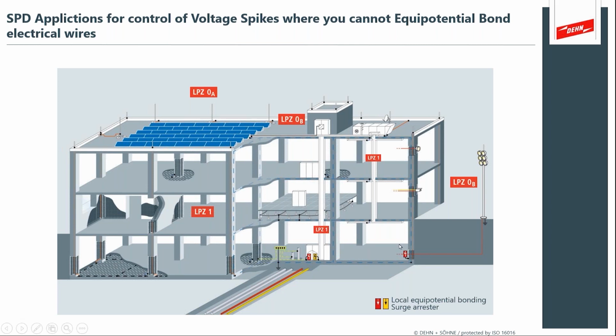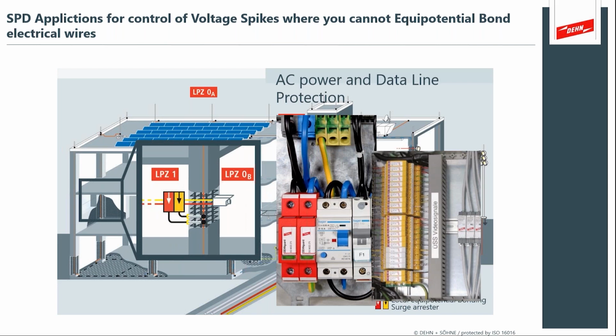And that's what an image like this is showing: you look at all of your apparatus and you apply appropriate surge protection methods. And in this instance, you can see a couple of nice images of the surge protection device at the electrical panel, which is right at that main distribution system, or at your low voltage control systems that have to be protected in the case of lightning currents being induced around it.